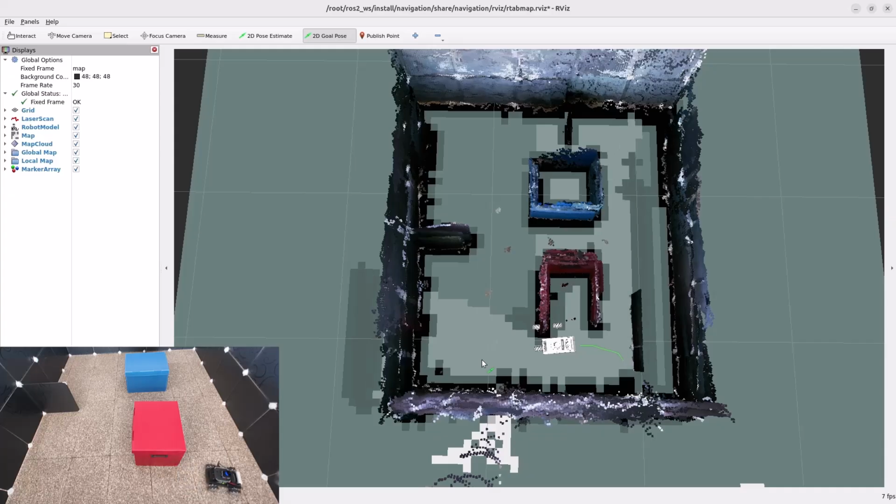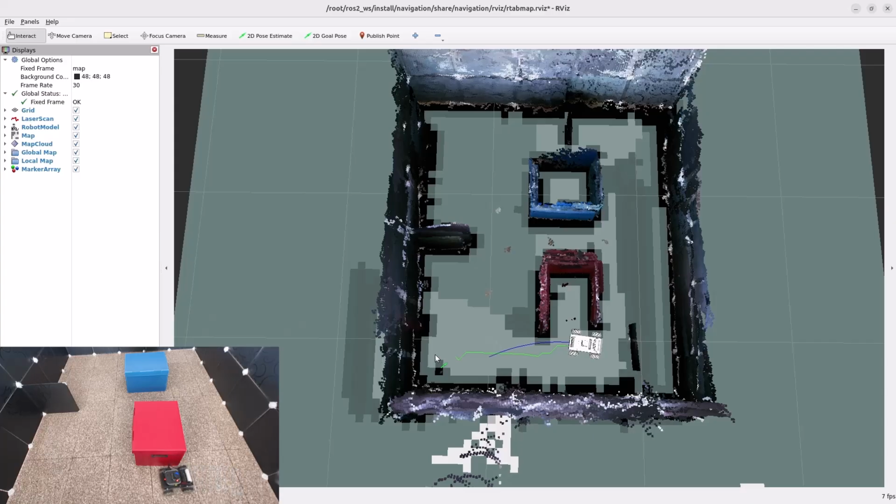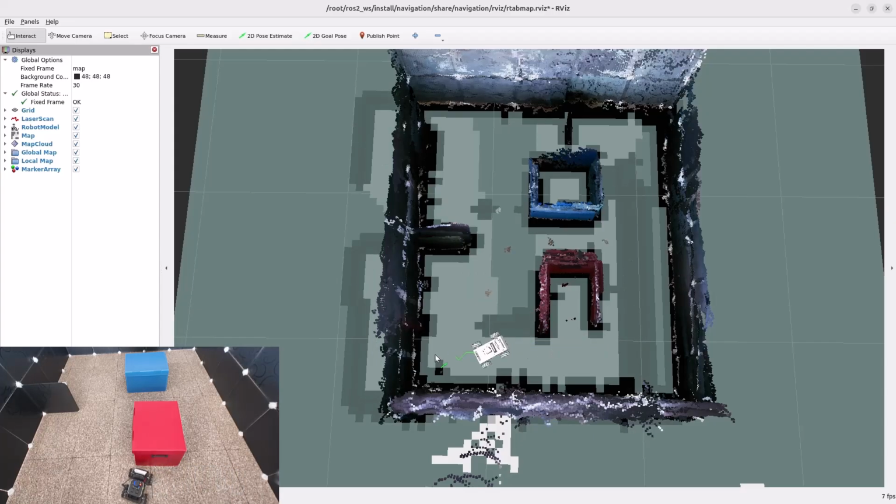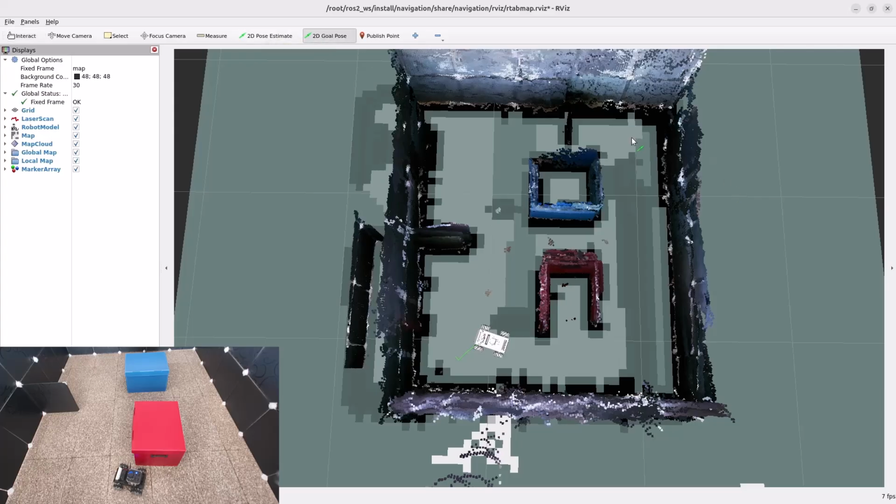One of the most impressive features is real-time obstacle avoidance. When the robot encounters an obstacle, whether it was in the original map or is a new obstacle, it automatically navigates around it. Watch as the robot adjusts its trajectory in real time, continuously updating its posture and path to avoid collisions while maintaining its goal of reaching the target point. The dark blue planned path updates dynamically as new obstacles are detected.